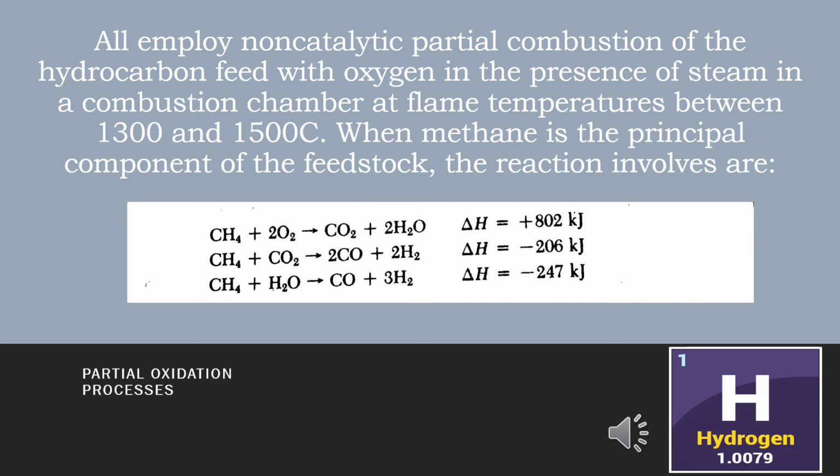It was originally developed by Texaco, and variations were introduced later by both Shell and Montecatini, which differ primarily in the design and operation of the partial oxidation burner. All employ non-catalytic partial combustion of the hydrocarbon feed with oxygen in the presence of steam in a combustion chamber at flame temperatures between 1300 and 1500 degrees Celsius when methane is the principal component of the feedstock.